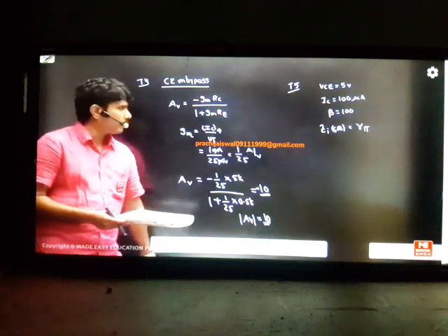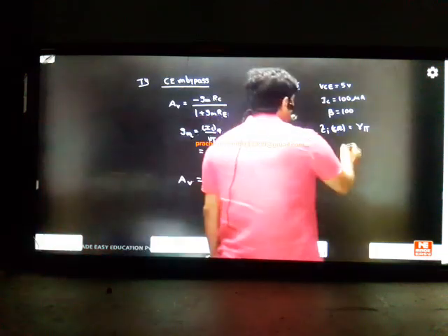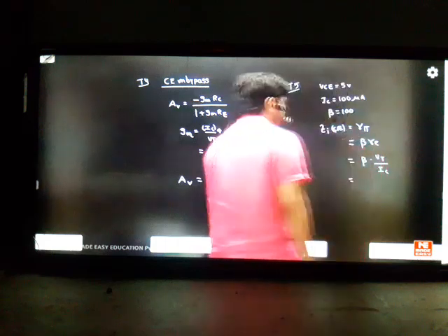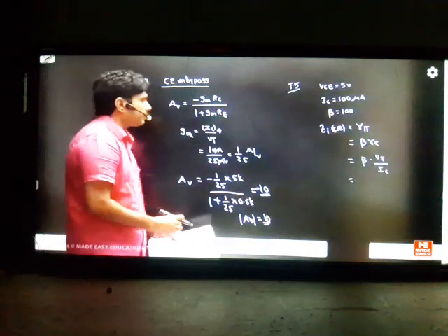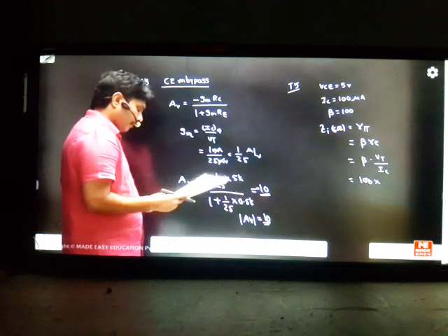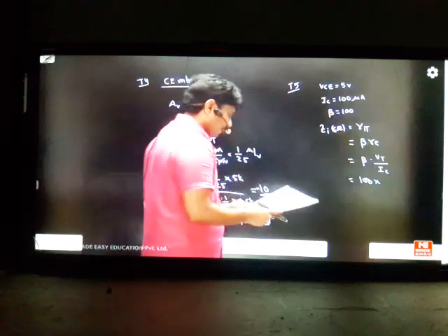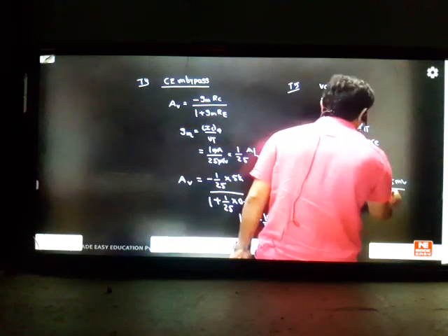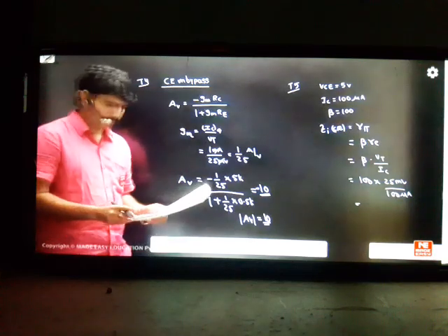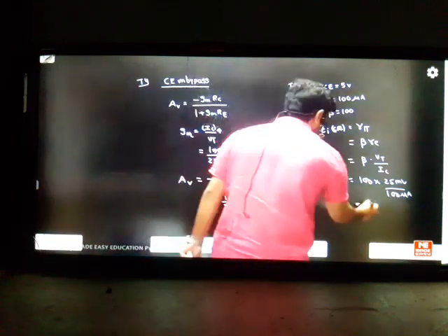Yeah, great. So if you see this one, T5 question is asking input impedance of common emitter. It is R pi is the input impedance. R pi can be written as simply beta times of Re. Beta times of Vt by Ic. So it's a simple problem. Ic is given already. Beta is given. So 100 into beta is 100. Vt in the problem, how much? It has not given Vt. So you can take 25 millivolts by 100 microamps. You can solve this answer. It's coming to be around 25 kilo ohms.